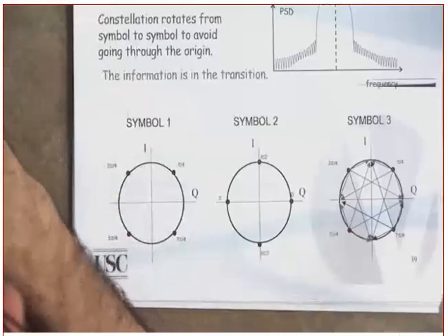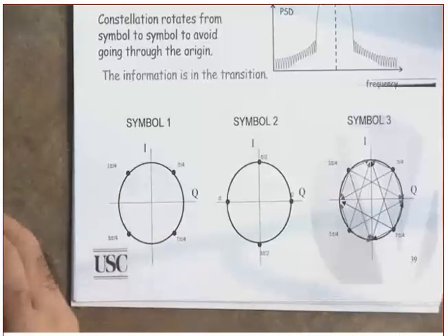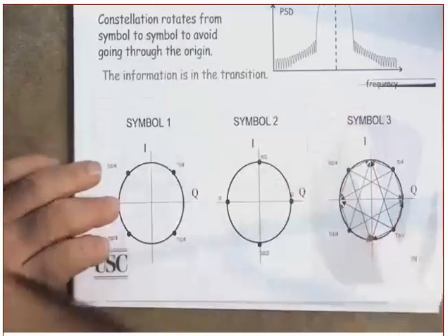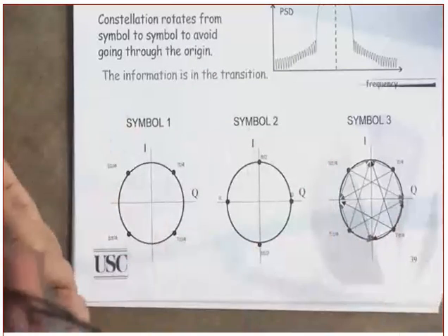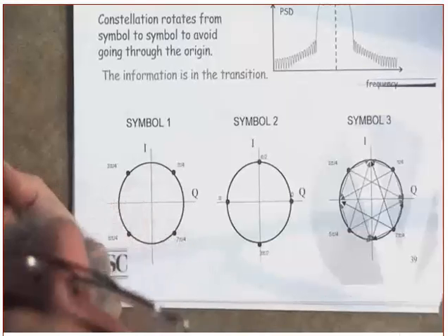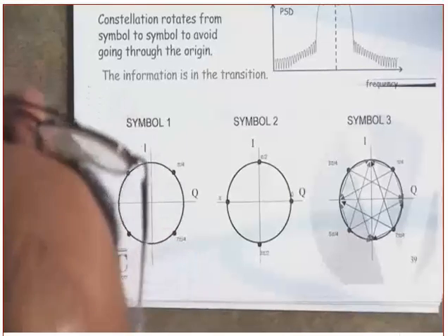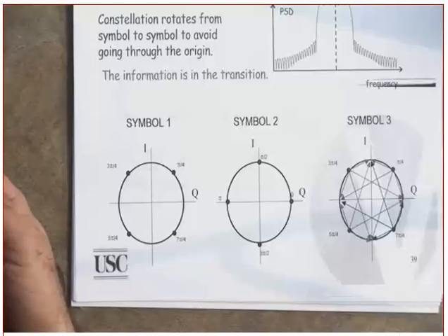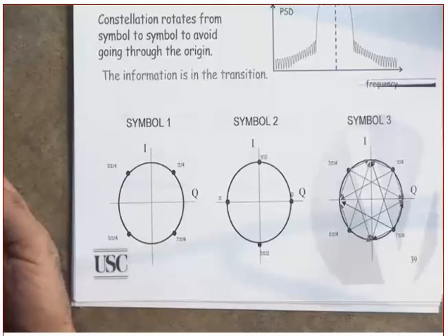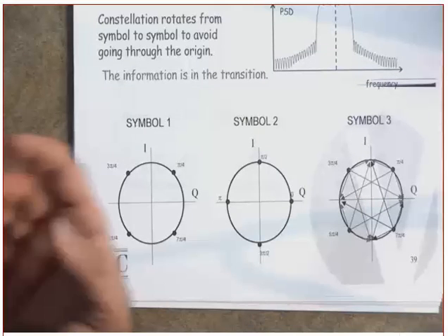I'm not talking about the carrier. I'm talking about the clock synchronization. It will be harder because there is no transition. It's just a straight line. Did you get this or not? The receiver would like to see transitions in the clock so that he can synchronize with those transitions. You follow me or not? Yes or no? You are losing me? Okay.